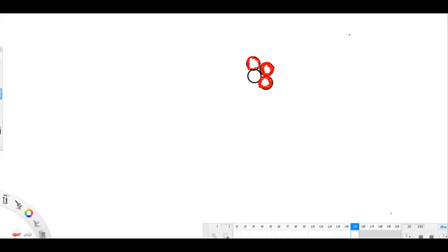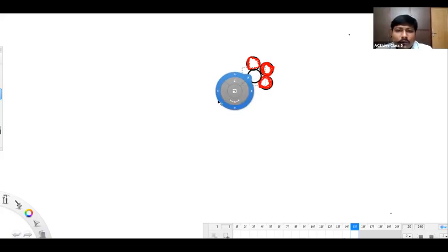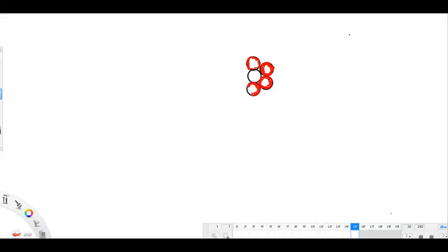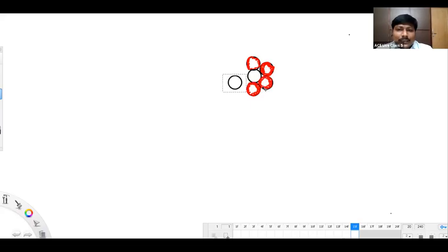In which conductor is the red color portion more? Obviously, the AAC, the stranded one. So in that perspective, definitely skin effect will be reduced, but it won't come to zero.